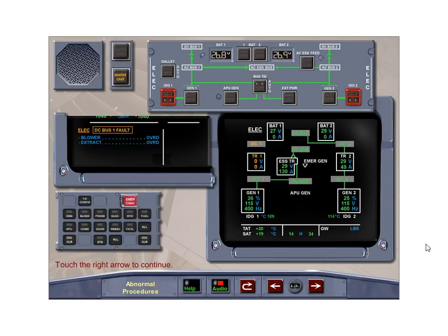With the DC Bus 1 fault, the DC Essential bus, normally supplied by DC Bus 1, is now automatically supplied by the Essential TR. The DC battery bus, normally supplied by DC Bus 1, is now automatically supplied by DC Bus 2. There are no ECAM actions directly related to the electrical system, as all switching is automatic. The status page lists all the in-op systems. Refer to FCOM 3.02.24, Abnormal and Emergency Procedures.